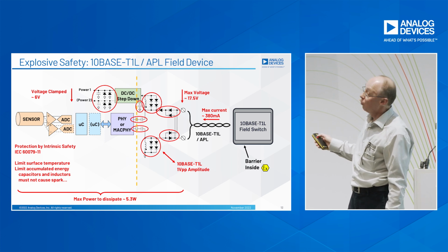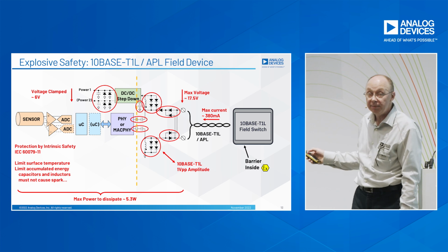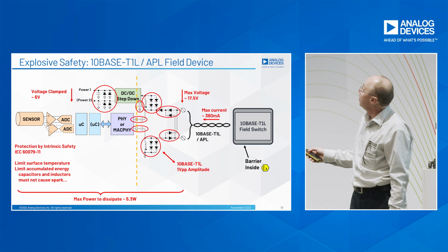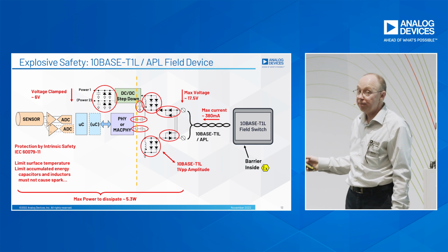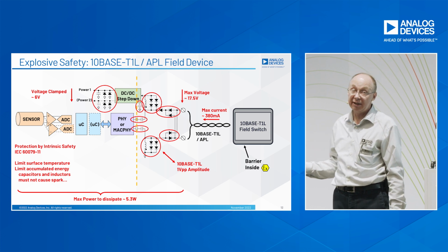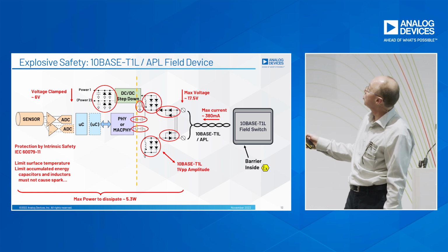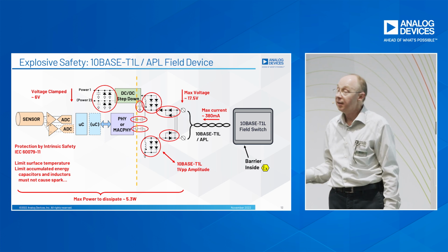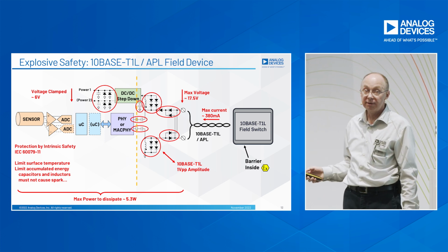And it says how much voltage can be expected, how much current can be expected to go to the device. There's some more protection needed for the power coupling. And you can see a large number of diodes there. There have to be 2 columns of diodes in parallel just in case one of the diodes fails. The other still needs to be able to clamp.